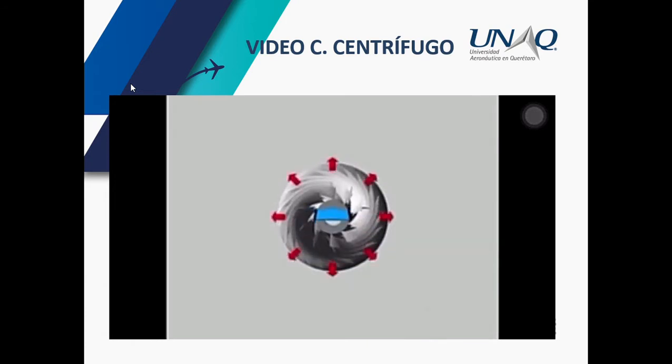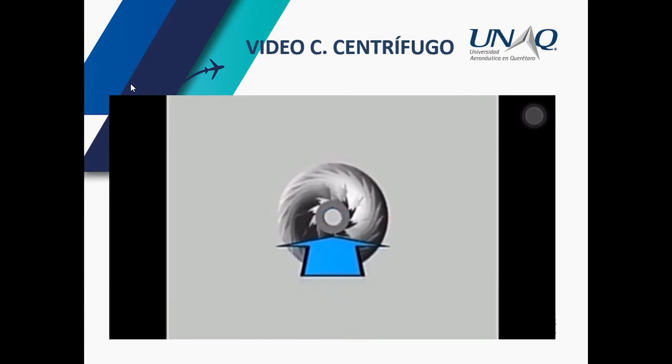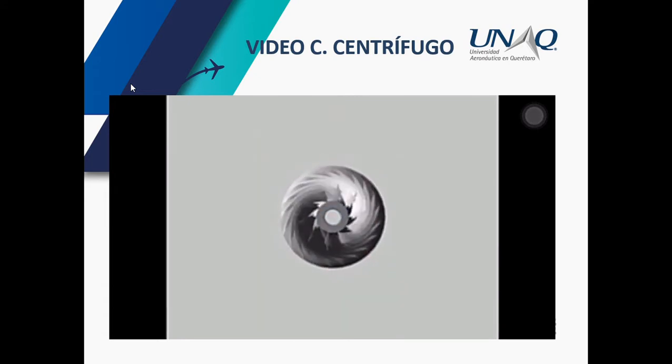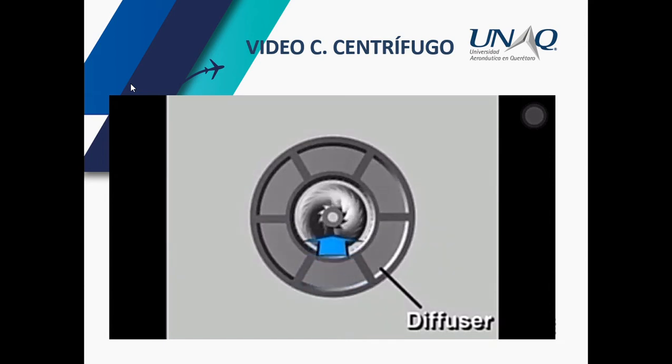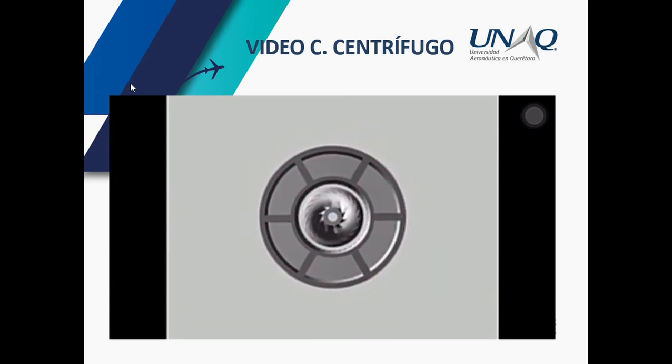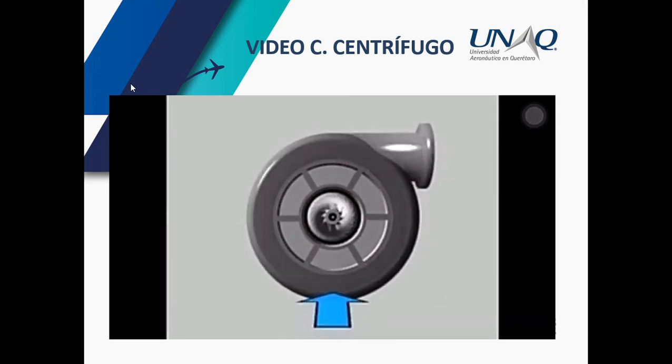To achieve the desired pressure increase, or compression, the vapor must be slowed down, converting its velocity pressure to static pressure. That's where the diffuser comes in. As high-velocity vapor moves radially outward through the diffuser, the flow area increases, slowing the vapor and increasing the static pressure. Some centrifugal models have diffusers with vanes or pipes which change flow direction and further slow the vapor. The volute-shaped casing collects the slow-moving, high-pressure vapor from around the diffuser and conveys it to the discharge connection of the compressor.